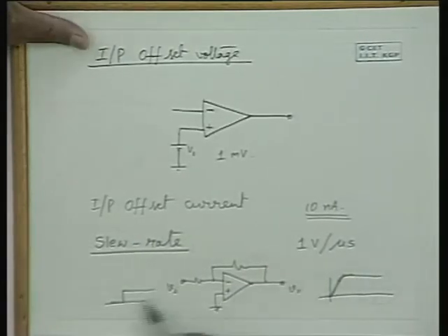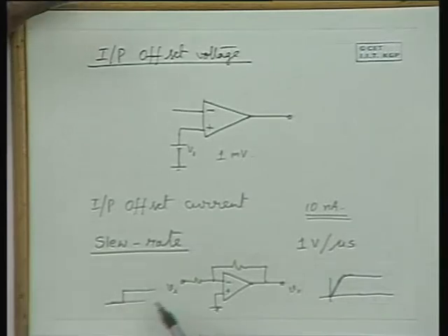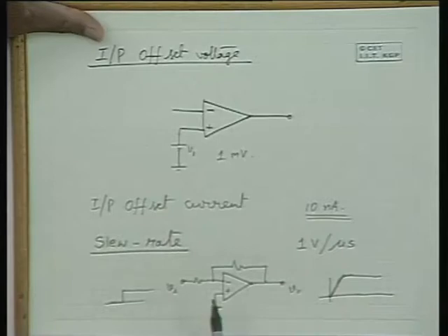For the output also to rise instantaneously, the amplifier should be a high frequency amplifier, a wideband amplifier. But because the bandwidth is fixed and the amplifier responds slowly, or to a lesser extent, for high frequencies, the output rises slowly.